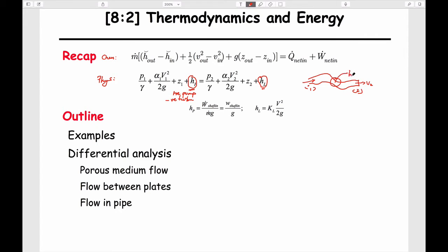We could imagine putting this pump head in here, and typically the head losses are thought of as basically frictional losses due to flowing within here, which is the head loss that occurs along the length of it. And we drew this little diagram last time to add each of these terms together at the upstream portion to represent the individual heads plus the pump head at the upstream location, and then stack them all up on the right-hand side plus the head losses at the downstream location.